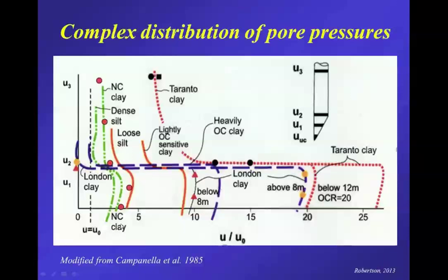You can see that in normally consolidated clays, you get quite large pore pressures, maybe 3 to 4 times hydrostatic, and then behind the sleeve it drops just a little bit. You still get pretty large pore pressures. In over-consolidated clays, the tip resistance becomes much larger, so the pore pressure on the face gets bigger. It can be 10, 15, 20 times hydrostatic, so you can get very large pore pressures on the face of the cone.